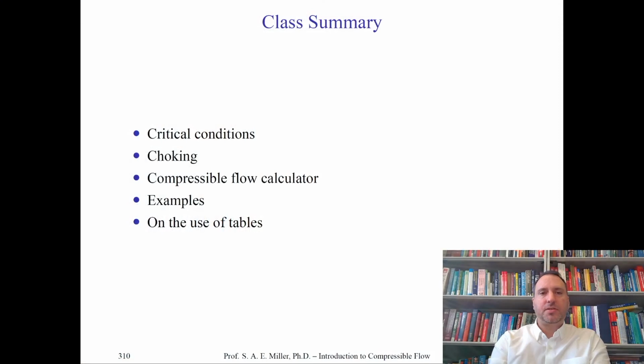In this class, we defined and derived the so-called critical conditions. And we looked at how these critical conditions are related to choking or the transonic condition of converging-diverging ducts, which correspond to the minimum area of the area-Mach number relation. We then looked briefly at a few examples and explained two particular numerical methods, that is, tabulated use of tables or the